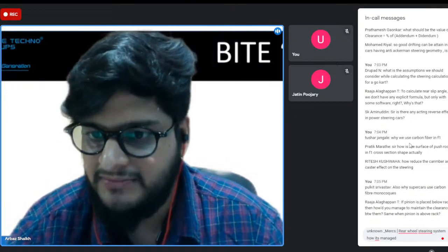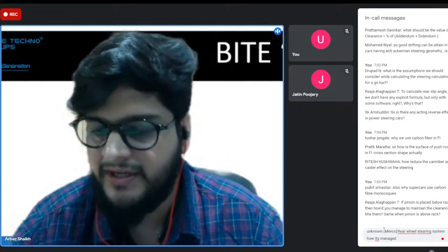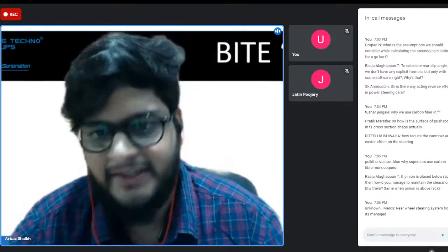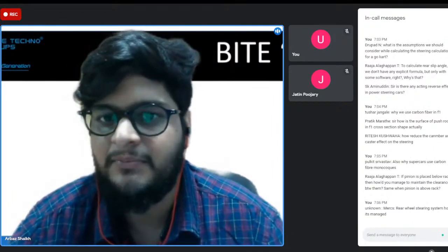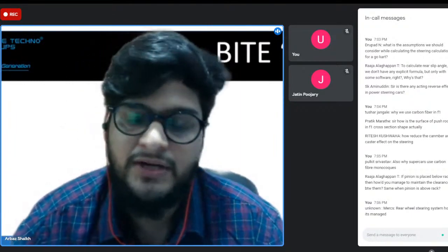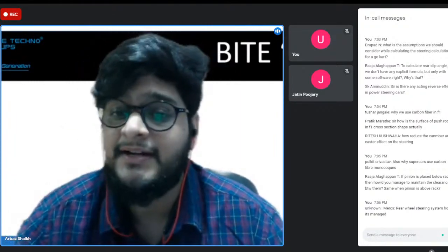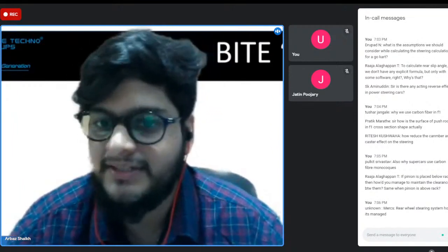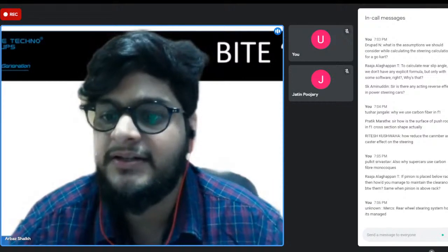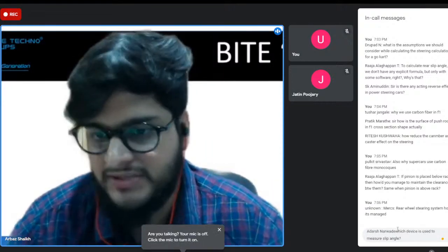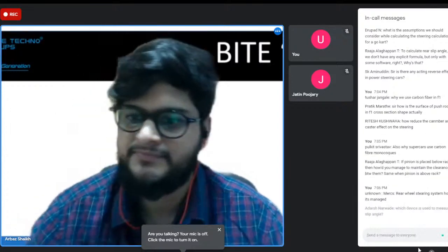Okay, Sean is asking, in which type of geometry, Ackerman or anti-Ackerman, can we do better drift? We can do better drift on anti-Ackerman geometry, definitely. It depends upon slip angle, right? If you arrange your geometry in such a way that you let slip angle overtake your turning angle, your vehicle will slide more and the centrifugal force will be more than your centripetal force, and you can drift better.